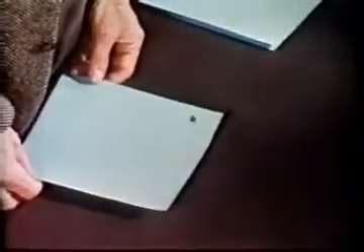Holding this sheet of paper horizontal, I give it a slight forward movement and drop it. It slides quite a distance. As it settles, the air is forced out of the narrow space between it and the table. The tangential stress so produced enables enough pressure to be built up beneath the notepaper to support it for a time. And during that time, the friction retarding sideways motion is very small.